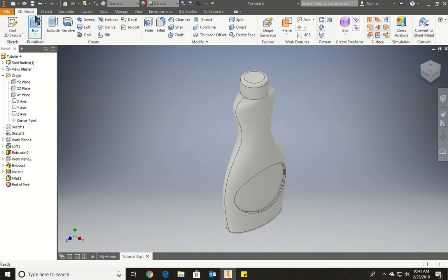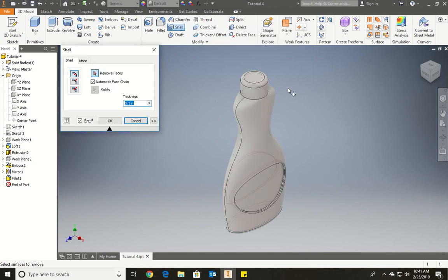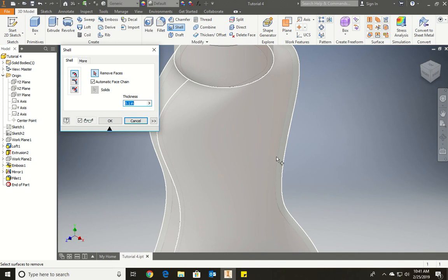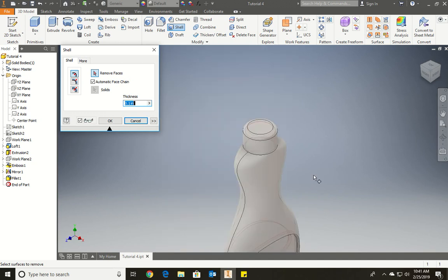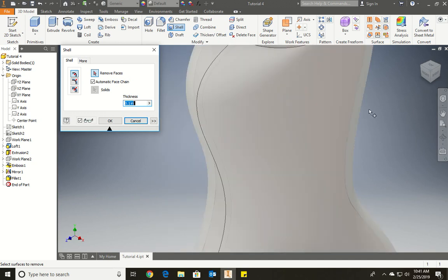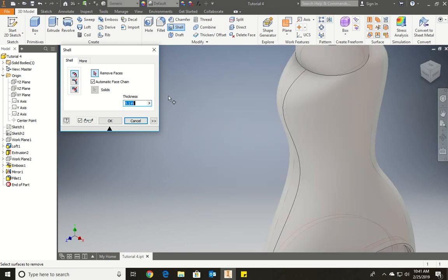Once we've completed the fillet, we're going to use the shell option again, found under the modify. Well, I don't see it right now. Sorry, below chamfer. Even if you look at the screen too long, you start not seeing things. And again, right away you notice it's already shelling my piece. I see the little red, a little bit red with the thickness that I'm choosing. The thickness we're going to use, I think, is going to be 0.03.